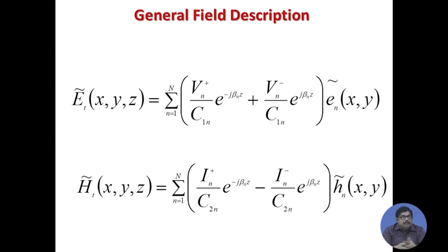So, you can find out their values and put those values in. There can be various modes possible, particularly near the discontinuity, or near the excitation, when we are very near to the source or very near to the load or very near to any discontinuity. Instead of a single mode, various higher order modes are also present. At that time we can write that in the form of various modal voltages and currents. This is the description, and this completes how you can define equivalent voltage and current at microwave frequencies.